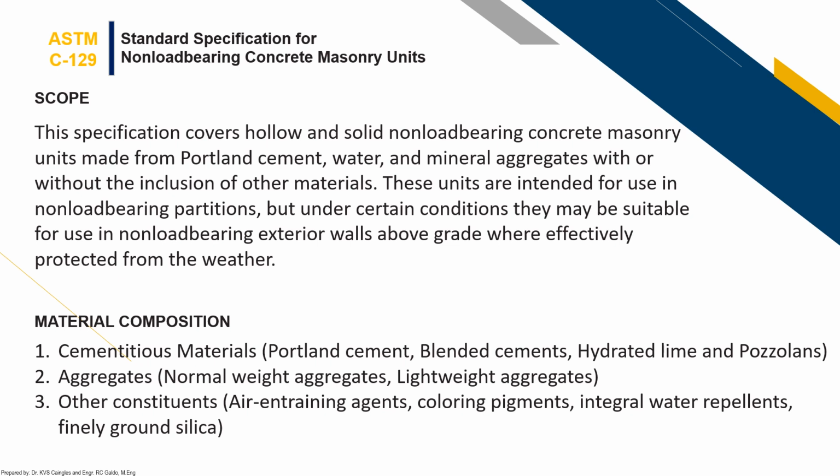First, we talk about the standard specification for non-load bearing concrete masonry units, or ASTM C129. This specification covers hollow and solid non-load bearing concrete masonry units made from Portland cement, water, and mineral aggregates with or without the inclusion of other materials.